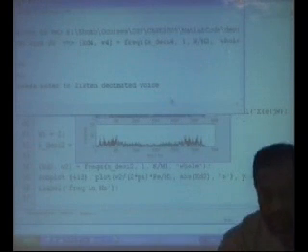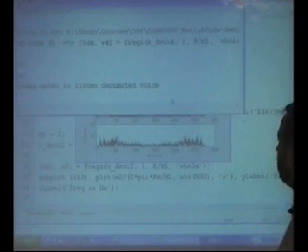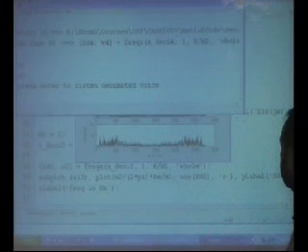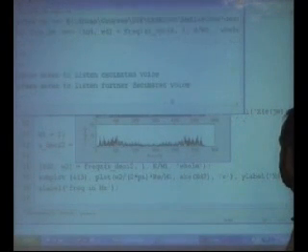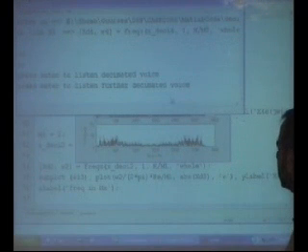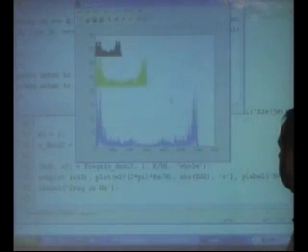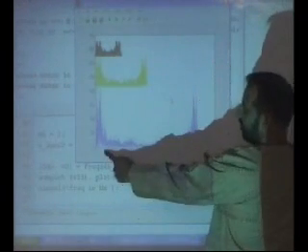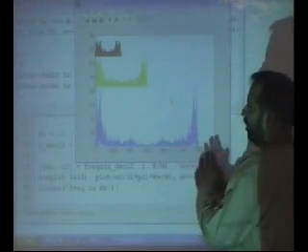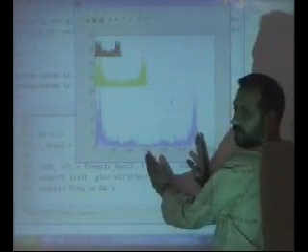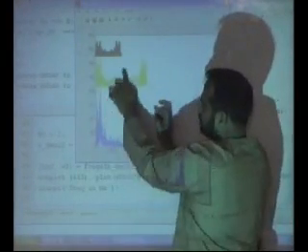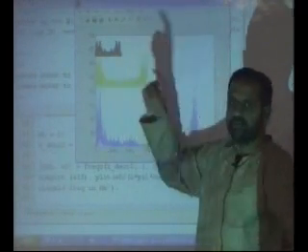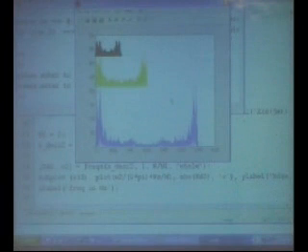Welcome to DSP1. So this is the decimated version. Obviously the speech quality will degrade because there will be some aliasing, but this is a better representation. This is the original spectrum. Once you decimate it by 2, you cut it down and move it like this. There is some aliasing here, but still the original voice activity is in this region. Though there is some aliasing, you will find some degradation in voice, but still acceptable perhaps.